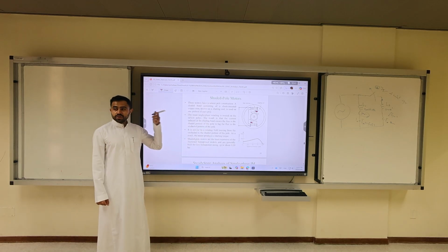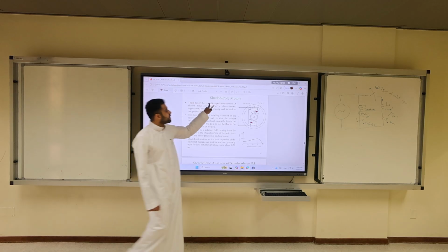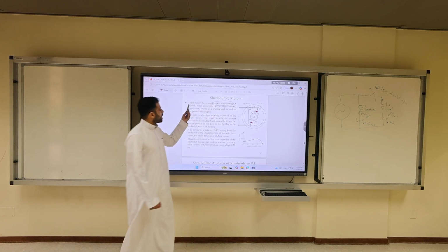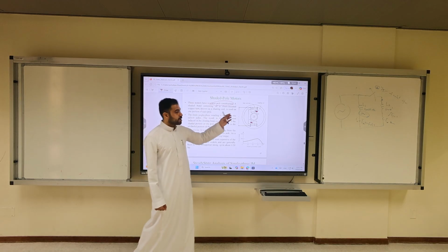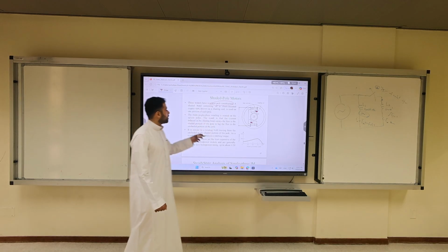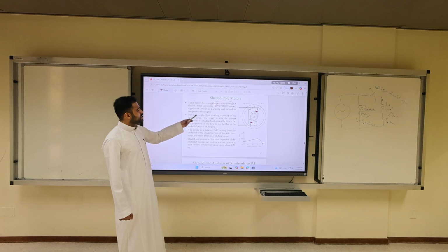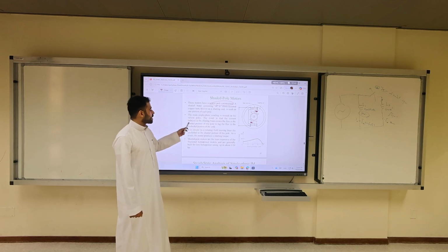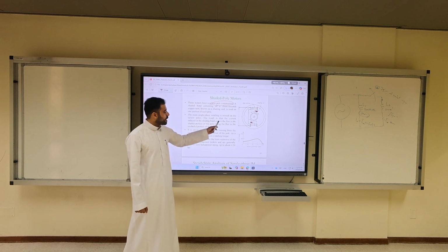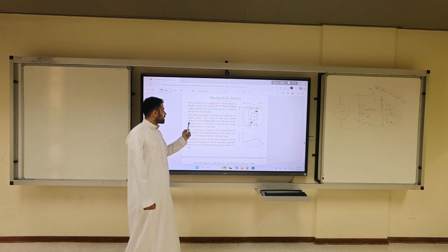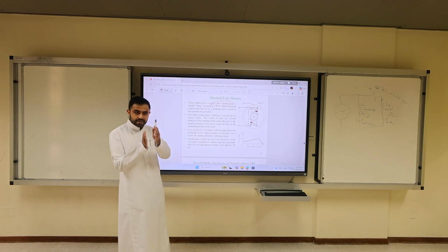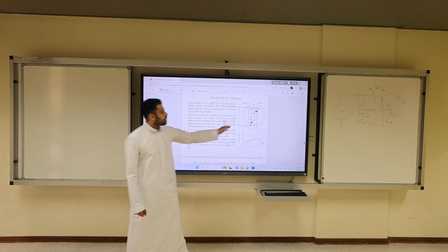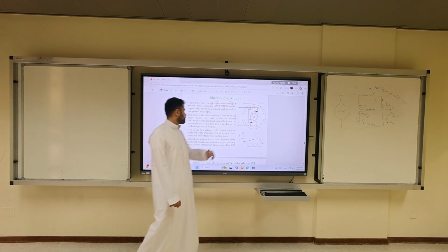What is the necessary condition for shaded pole? It has to have a salient pole construction. A shaded band consisting of short-circuited copper turn. This is the shading coil, shading part of the pole. This is very important. The main single-phase winding is wound on the salient pole. The result is that the current induced in the shading band causes the flux in the shaded portion to be lagging, to be a different phase than the rest of the pole.